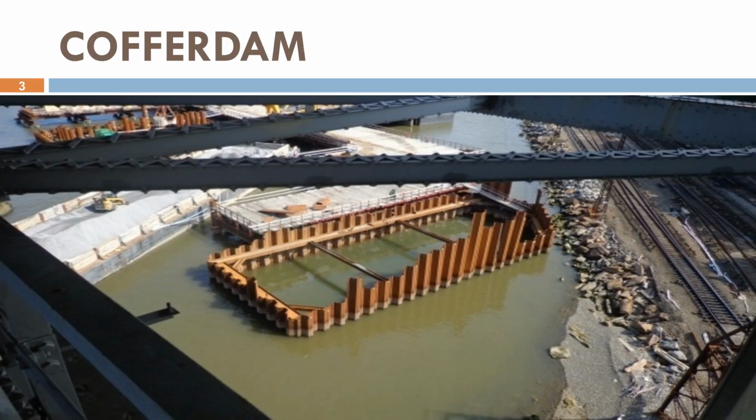This figure shows a typical cofferdam used during bridge foundation construction. Notice how the sheet piles form an enclosure around the foundation location. The water inside the enclosure is pumped out, creating a dry excavation area where engineers can safely carry out piling, reinforcement fixing, and concreting. Without a cofferdam, underwater concreting and excavation would become extremely difficult, expensive, and unsafe.